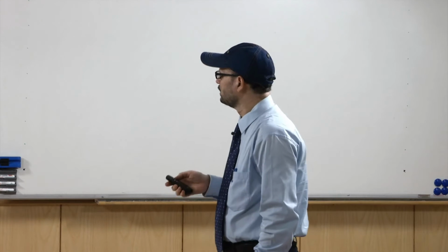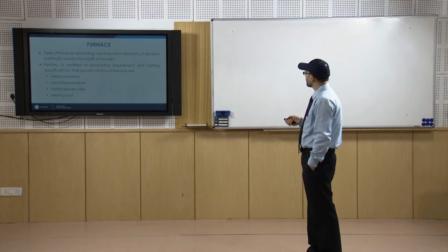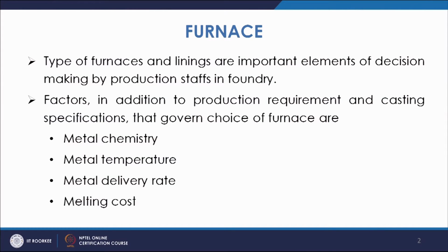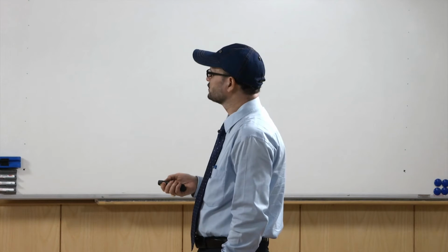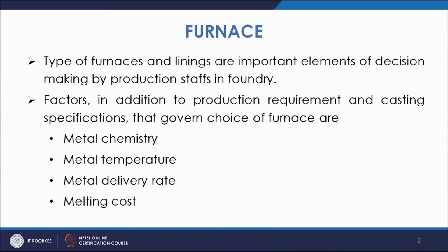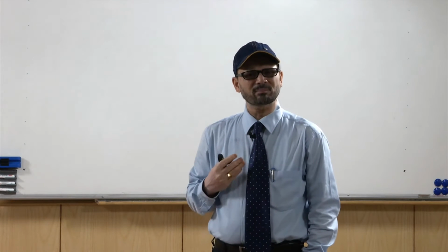In addition to the production requirements and casting specifications that govern the choice of furnace, the factors which are important are metal chemistry. What is the metal composition, what type of gases are going to be evolved, what kind of reactions may take place?